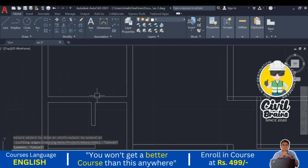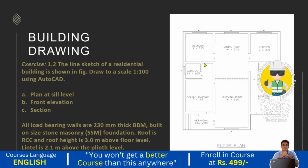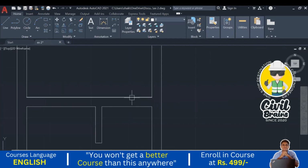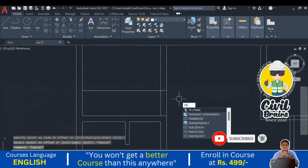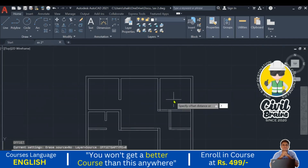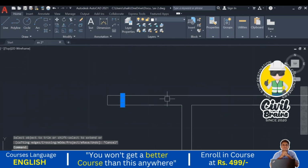Now next, for this bedroom, okay, from here it is one door, from here it is one door, two doors are there, and this is the opening, and one door and one door. Okay, fine. So we'll draw one door over here. For that one, we just extend this line to draw the door offset. What is that? D1. D1 is 1 meter. So enter. I just delete this one and delete this one. And similarly, I just go to the offset. This door 1 meter. Okay, I just trim this one. Trim this one. I just trim this one also. This is extra, I just delete it.